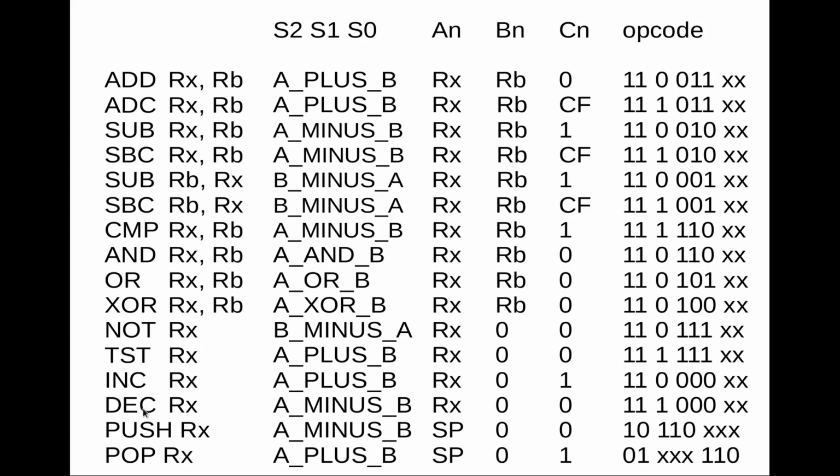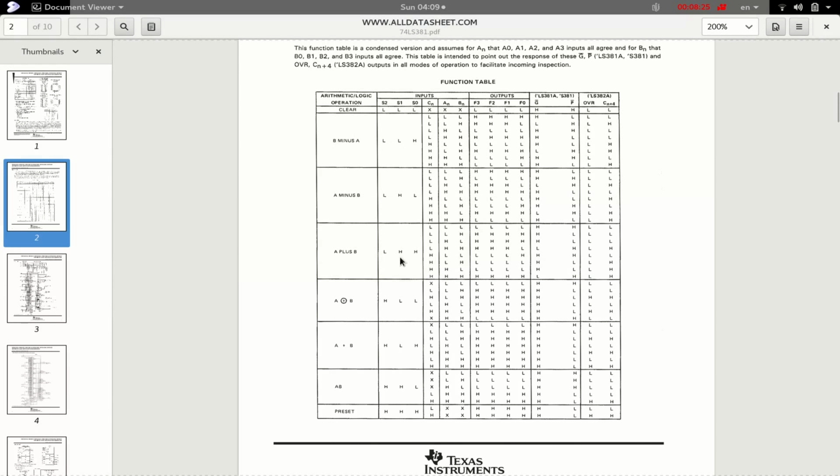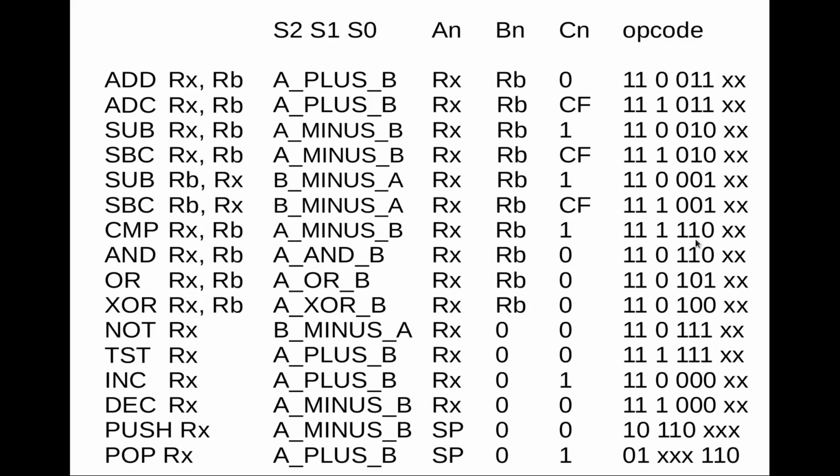And so now we have the increase and decrease instructions. Here we use the other combination of 3 bits, which for our chip has no meaning. For our opcode, that gives us some free space, which we can use to assign somewhere else. In this case, I've assigned those to the increase and the decrease instructions. The increase instruction is all zeros here, and that's an operation performed on a single operand. We already determined, when we looked at the ALU, that these are the actual signals which we need to send to the ALU in order for it to perform that increase. But in our opcode space, we'll assign it to this operation code of 0, 0, 0.